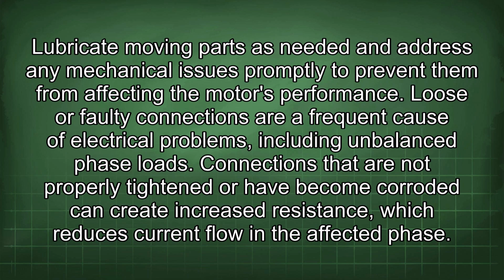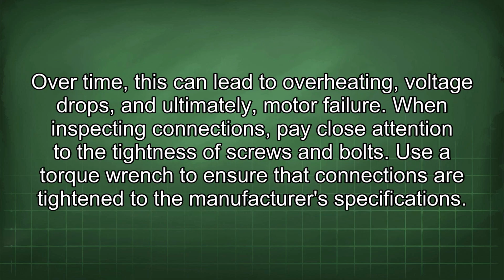Loose or faulty connections are a frequent cause of electrical problems, including unbalanced phase loads. Connections that are not properly tightened or have become corroded can create increased resistance, which reduces current flow in the affected phase. Over time, this can lead to overheating, voltage drops, and ultimately, motor failure.